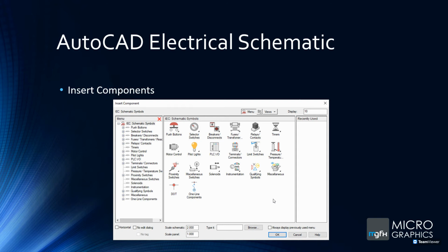They do have JIC, IEEE. So when you install the software, you just select which one you want to use, and to get this in, double click on it. It'll then put it into your drawing. Automatically cut the wire, as I said. You put it onto a wire, and then you'll be able to go and edit the component details that you've got on there as well.